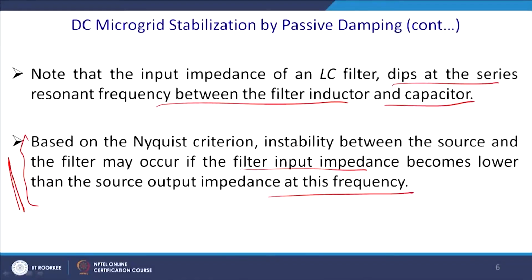So, you have chosen a particular switching frequency, and one layman kind of question sometimes asked is, what is the frequency in a DC microgrid? Because all these DC to DC converters are switching devices, they operate at a particular switching frequency, and you are required to filter out those high frequencies. While designing the filter, you require to remember this Nyquist criteria very well.